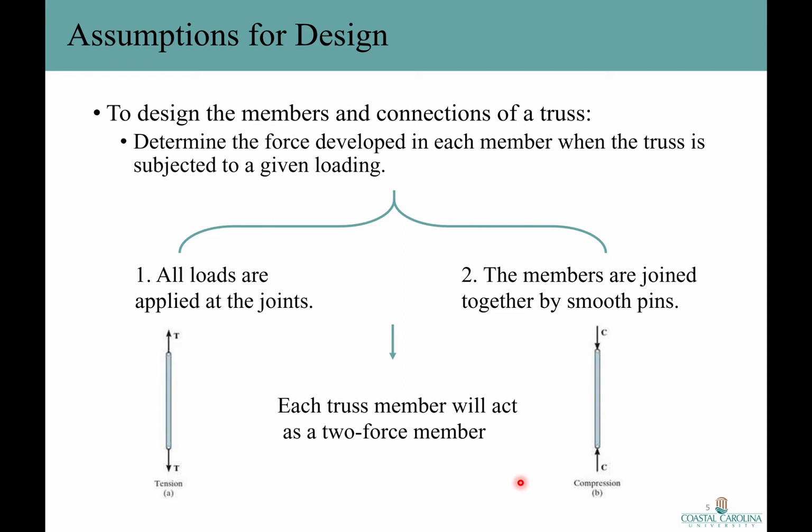In design of a truss, it is important to know whether the nature of a force is tensile or compressive, because usually compression members are made a little bit thicker than tension members because of the buckling or column effect, that you'll learn about in future structural courses.